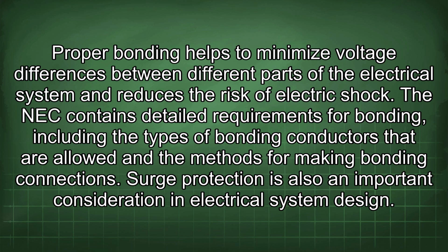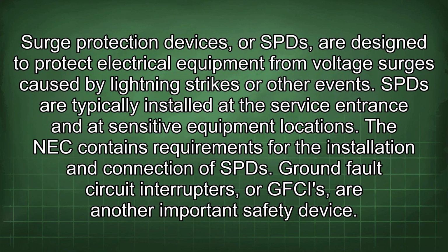The NEC contains detailed requirements for bonding, including the types of bonding conductors that are allowed and the methods for making bonding connections. Surge protection is also an important consideration in electrical system design. Surge protection devices, or SPDs, are designed to protect electrical equipment from voltage surges caused by lightning strikes or other events. SPDs are typically installed at the service entrance and at sensitive equipment locations. The NEC contains requirements for the installation and connection of SPDs.